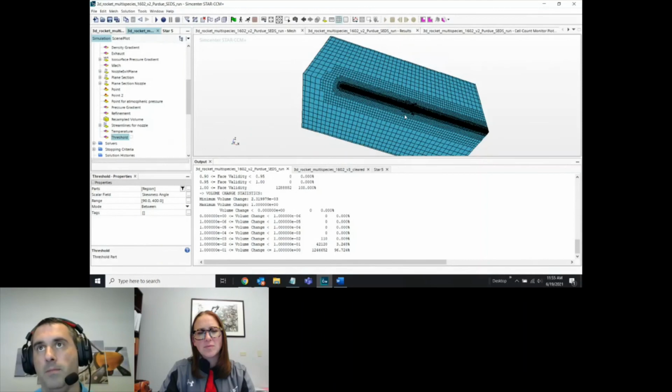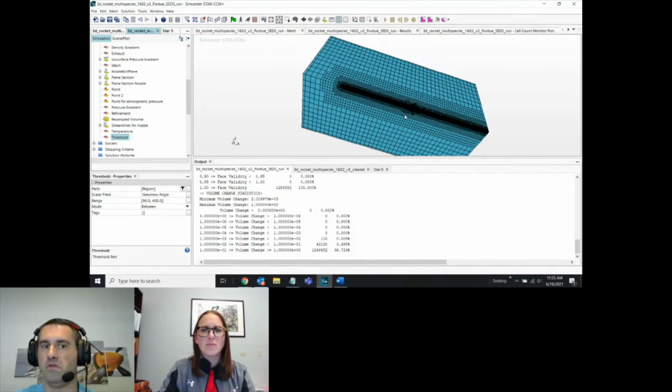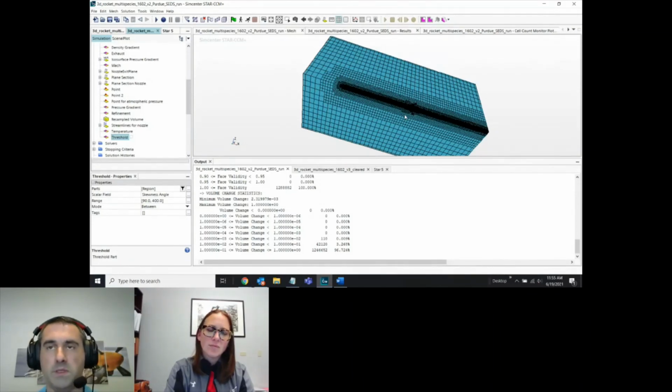So in certain scenarios where I've had complex geometry or really tight gaps to squeeze cells into, that's usually where you find those highly skewed cells. It'll highlight an area where you can go in and change the geometry, eliminate maybe little sliver cells, or really small gaps, or go in and refine the mesh so you don't have those problems.